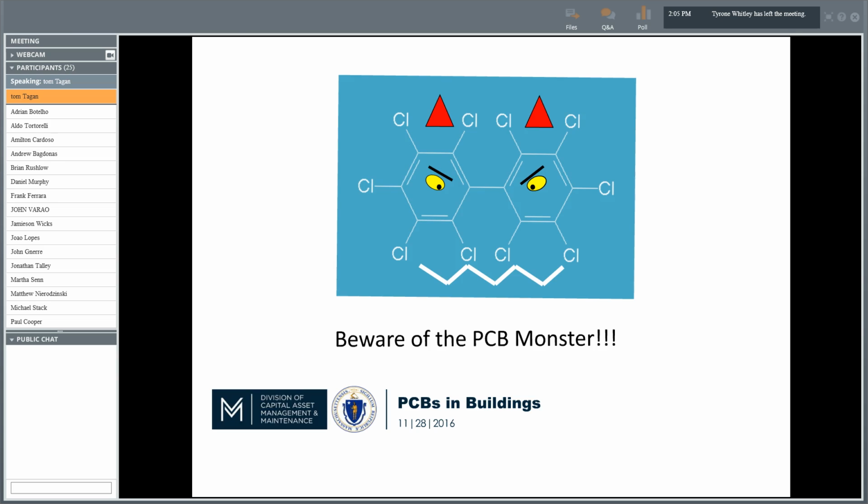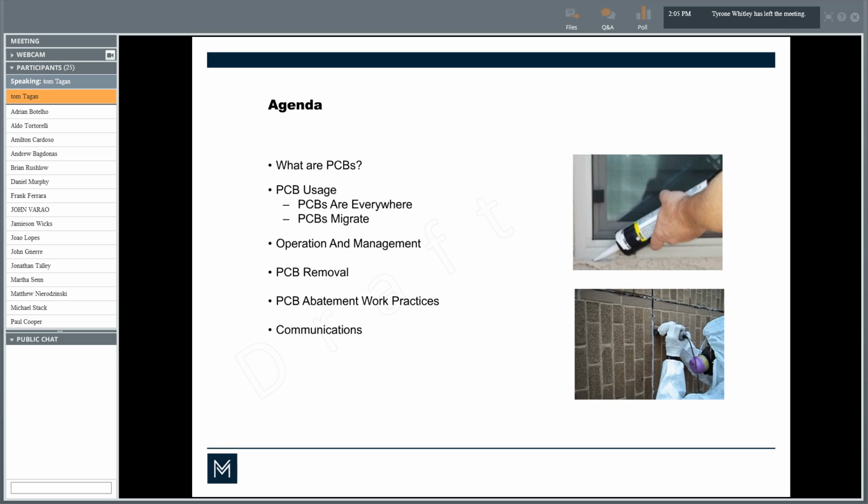I'll be back. The second part of this presentation is related to PCBs. PCBs are polychlorinated biphenyls, and they have become much more of an issue over the years, particularly in building materials. In the past, you focused on PCBs and oils. Transformers used them all the time. PCBs were great because you could let the oil heat up quite a bit and it would not break down as readily, so the oil did not need to be changed out of transformers more frequently. However, it has now become an issue inside of buildings, particularly related to caulk materials.